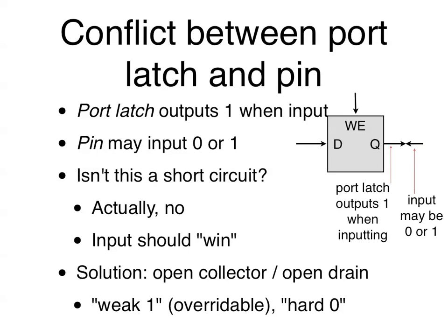Because the resistor is there to limit the current. But if you don't have the pull-up resistor and you just connect directly to power or ground, then yes, that could actually be a short circuit, in case they don't agree.